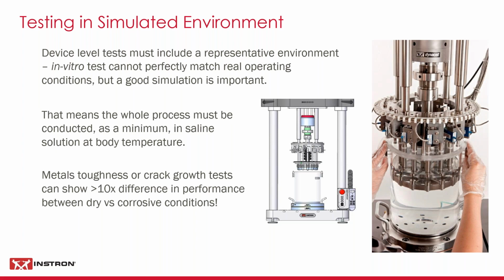And the point I've made at the bottom there is something that I certainly encounter from the materials testing world: when you look at fracture toughness or fatigue crack growth, you can actually get really very severe changes in the performance of a material between doing a test in dry air and doing it in corrosive conditions, even if that's as simple as in saline solution.